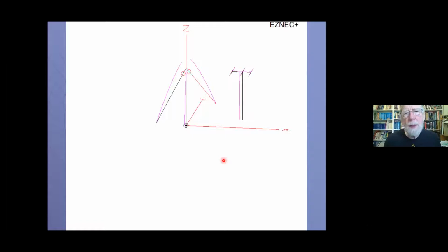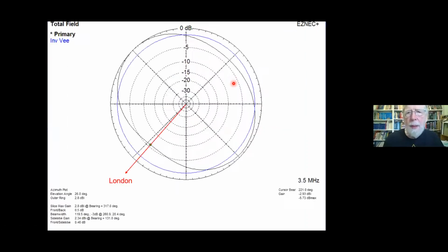And what happens when we excite this antenna, you can see the current on this tower is quite high. You can see this magenta line is quite a ways over from the tower line. And so you have quite a bit of current. You have some on the top, but this acts like a top-loaded vertical, really, which is resonant. Now, I chose these things to be a kind of a worst case to illustrate the phenomenon. And what happens to our pattern now is that we've lost about 4 dB or so.